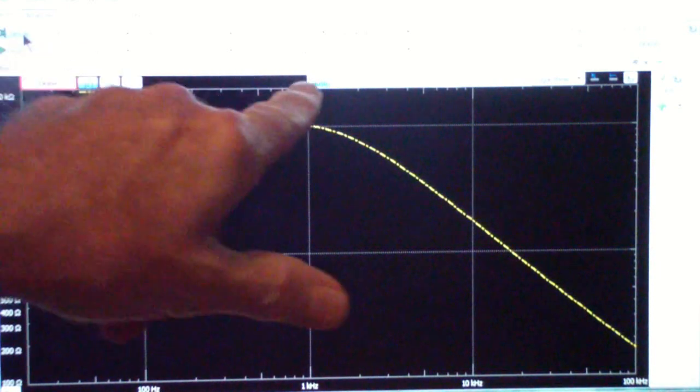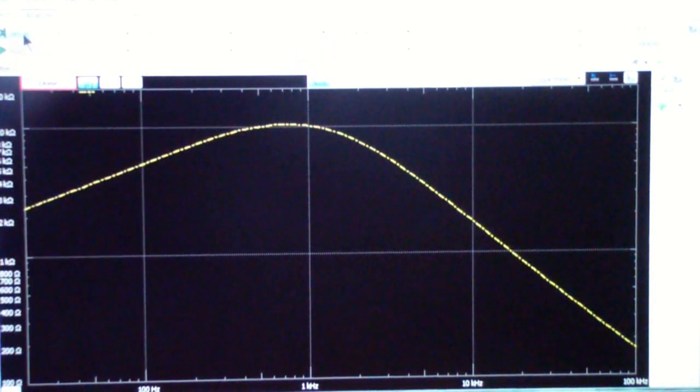So how did we fix it? Well, we just raised the resistor value to 100 ohms, and it fixed both. So I think putting resistor too high or resistor too low on there is misleading, and I suggest that Digilent change that to perhaps resistor too high or low, or resistor not correct, or something like that, because it's misleading.